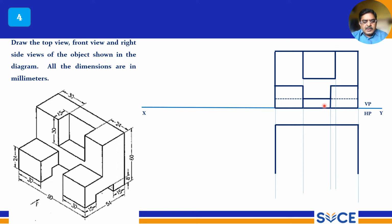You have to draw the top view. It will be like a C shape. So you have to complete this like this. Then there is an invisible edge, the through hole. The through hole is invisible, so you have to draw the dotted line.